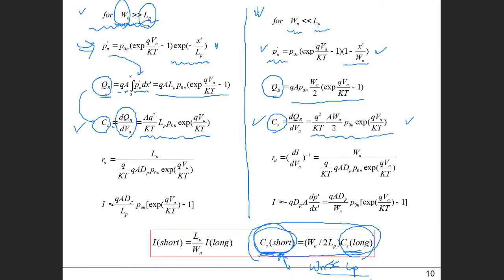This characteristic is especially important. Later on, we're going to study the switching characteristic of this PN junction diode. When you look at how fast a diode operates, that characteristic is directly related to this capacitance. A smaller capacitance supports faster operation of the device.